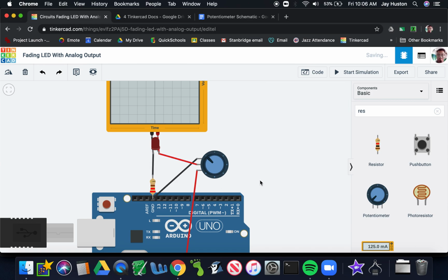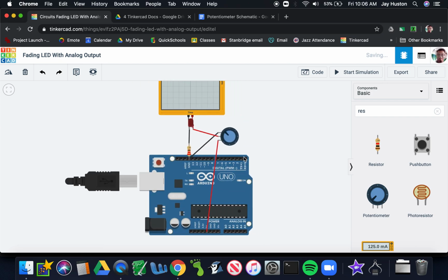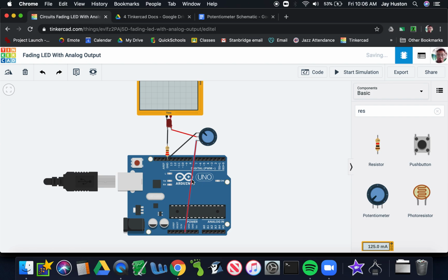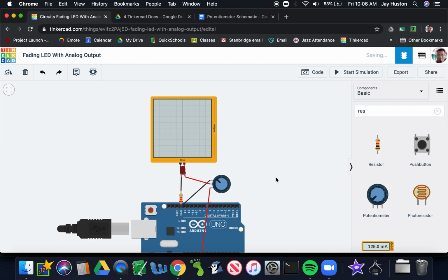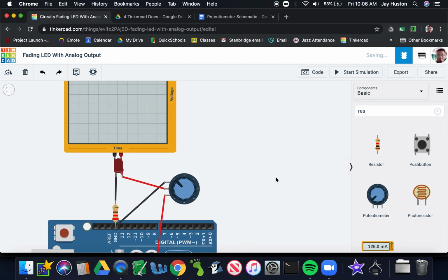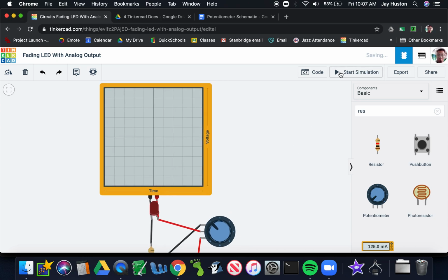And now the path, just so we can look at this path, the power comes in here. It goes into the potentiometer. It goes through the resistive strip until it hits the wiper, being this line right here. Then it exits and enters the LED and then goes home. So let's see what that looks like. Let's zoom in just a smidge. Clearly I'm not very good at zooming. There we go.